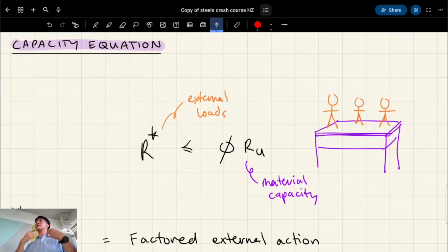It's about introducing safety factors, basically. Because if we can exactly support 300 kilos and there's 300 kilos on it, well, you didn't design it properly, because if this is considered a reasonable load on it, it's going to break. But that's why we have this star here, essentially.